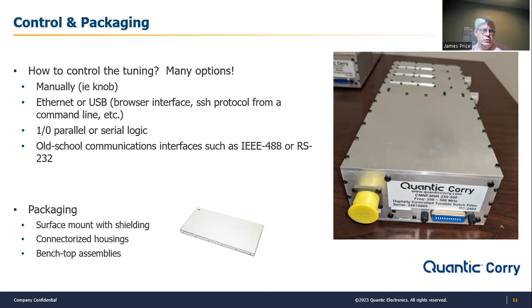You can control them with 1-0 IO logic, just TTL or 3.3 volt logic or what have you, parallel or serial clock or latch in commands into the unit to command it to the frequency of interest. Or you could go old school communication style, go with IEEE 488 buses, RS-232. Some of those kinds of things are also definitely possibilities.